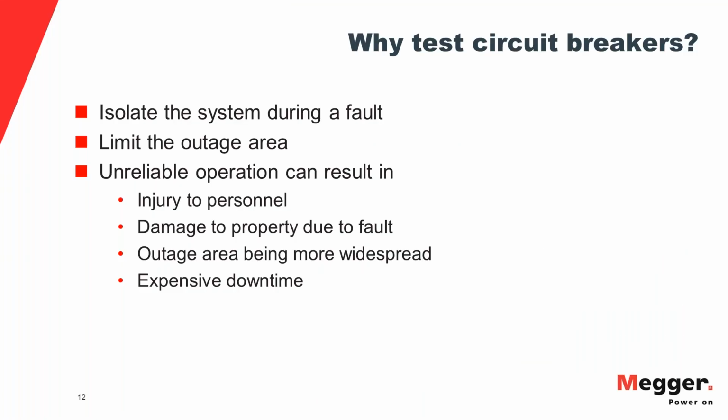Before we get into the actual tests, let's talk about why we need to test circuit breakers. Circuit breakers, as I said, form the arm of a protection system. They isolate the fault. They protect the system from faults. If they have the right selective coordination, they can limit the outage area to a minimum.